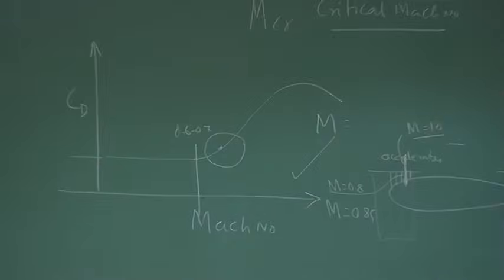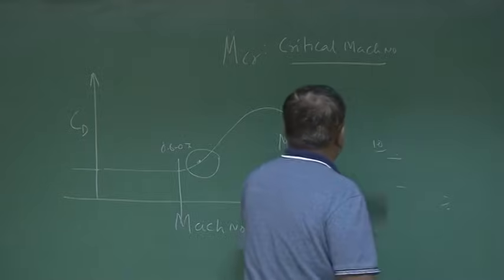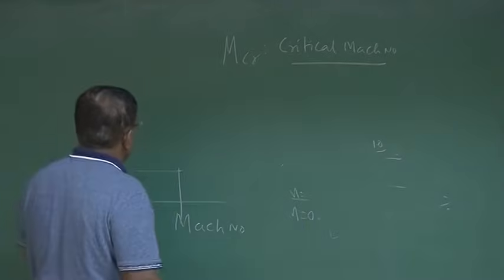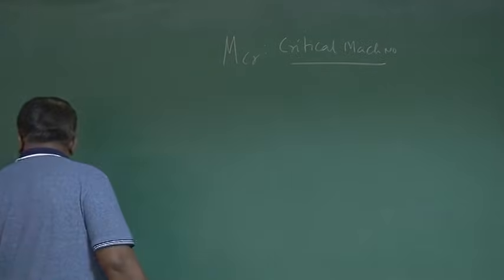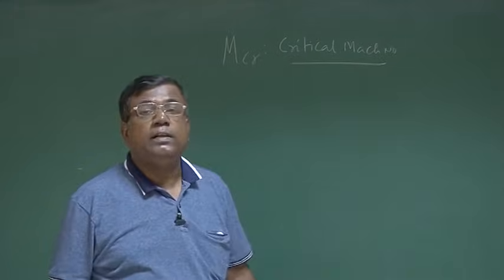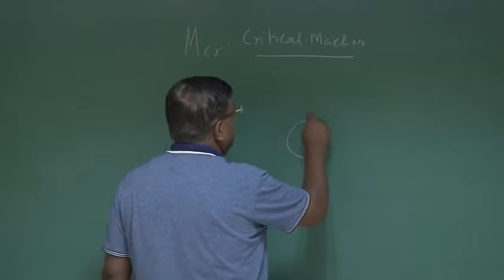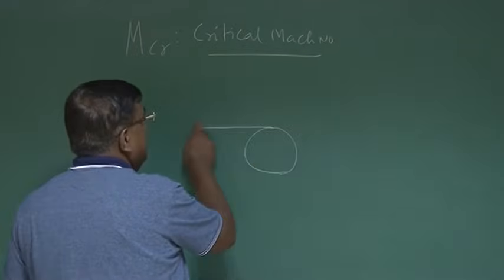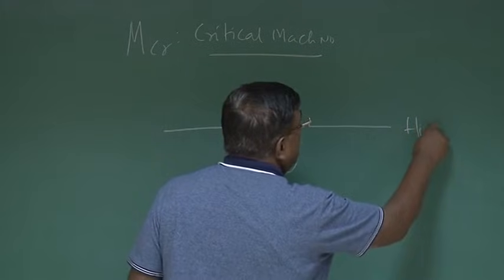Right? In the design of the wing and its layout, you will also see a few configurations which may draw your attention, which should at least help you ask the question why this wing is like this. For example, if this is the fuselage, I can have a wing like this, which is called high wing.